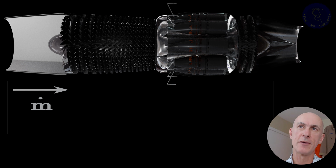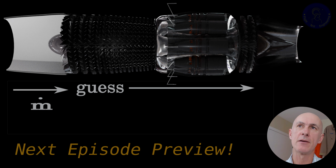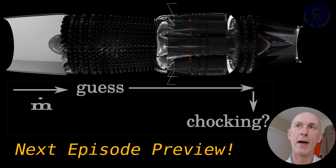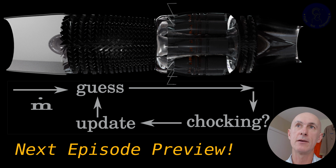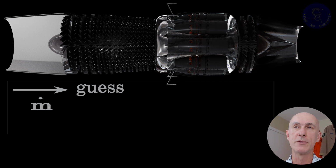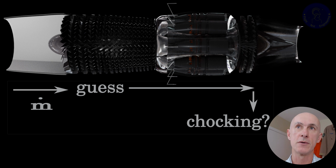As I said before, this concept of mass flow being limited is extremely important because even if the compressor is trying to push more mass flow through the turbine, with the nozzle choked, this increase will be limited. Keep this in mind until the next episode, where we will go back and revisit the inlet mass flow assumption and create an iterative version of the code to obtain convergence, considering what is going on in the nozzle throat.